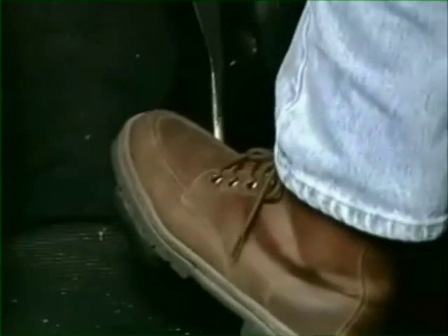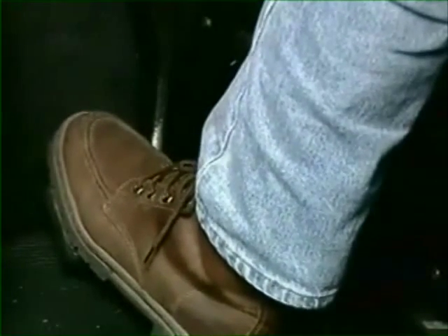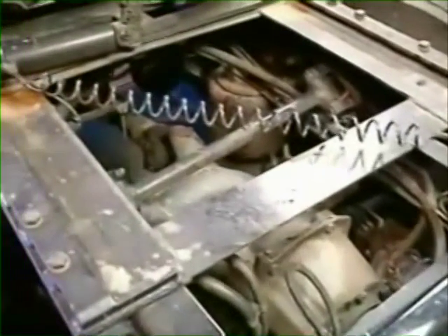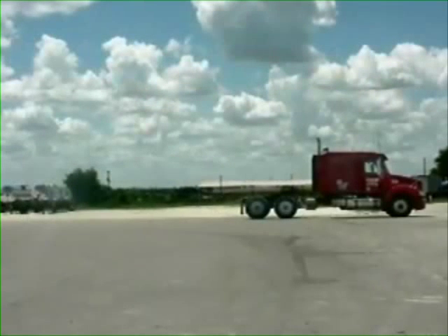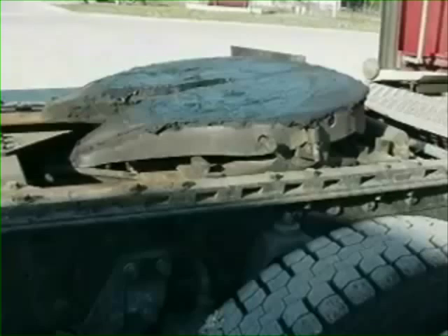Vibrations that can be eliminated by engaging the clutch at road speed are probably being induced by either the engine or driveline. If a vibration is eliminated by dropping the trailer, then the source is usually the trailer's tire wheel assemblies or the location of the fifth wheel.